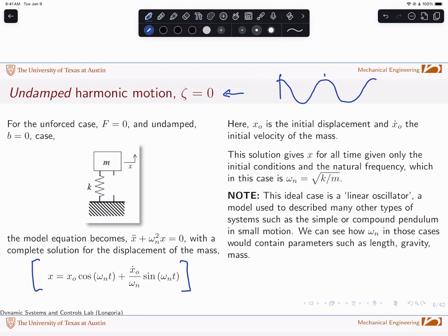And so only in this case could you approximate that period right there as the undamped natural period, which would allow you to estimate the omega sub n. In most cases, if you measure this period, it's the damped period. So you need to know two things, right? You need to know zeta and omega n. And so you can't determine parameters without making more estimates. In the undamped case, though, you can. You can right away estimate omega n just from one measurement. And it's a very nice approximation, right, if you're just doing quick back of the envelope calculations.